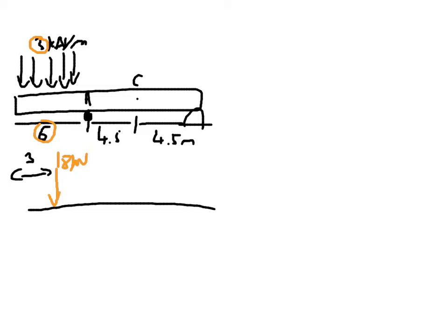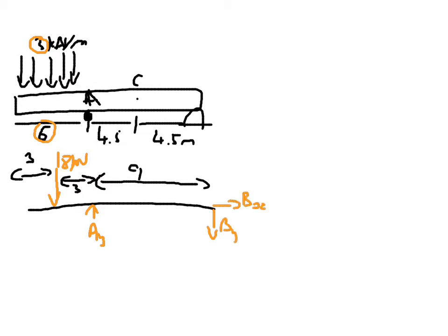We've also got a rolling joint at point A, that's meant to be an A just here, and A is 6 metres in, so another 3 in from the 18. We're going to have another force, a support force in the Y direction, AY, and finally another 9 metres, so 2 times 4.5 in. At B, we're going to have a BY, and we're going to have a BX, because that is a pin joint. And we want to know the forces acting.